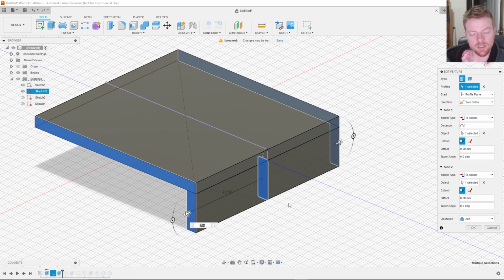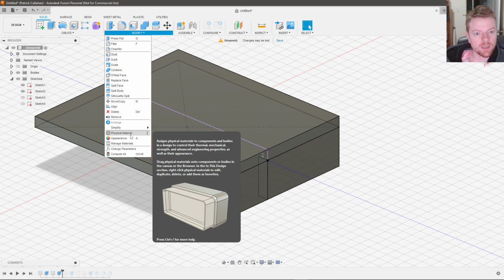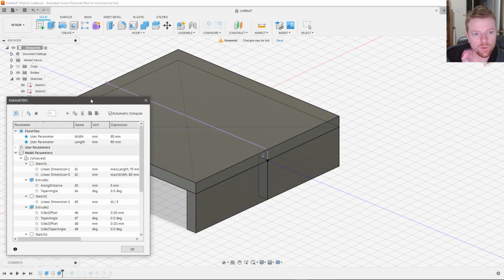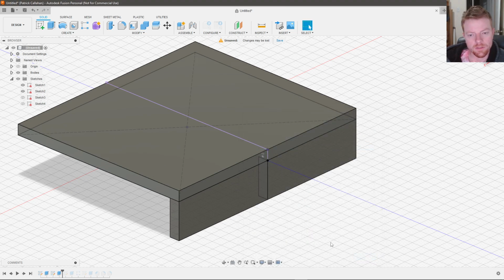So once again, now that width of that extrusion is being defined by those outer faces of that extruded rectangle, such that if I change the first rectangle, those will update automatically because they're dependent on it. So just to give you a visual example of that, once again, if I go into here and I change this to 105, my width changes and my extrusions automatically update.